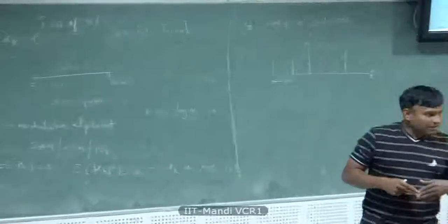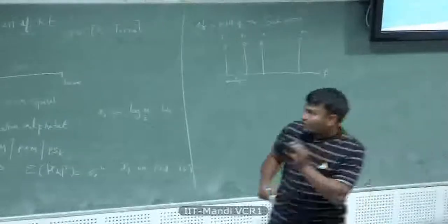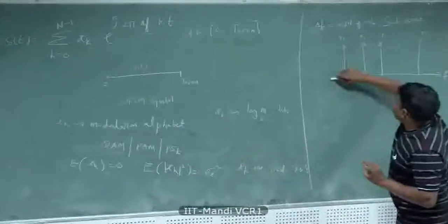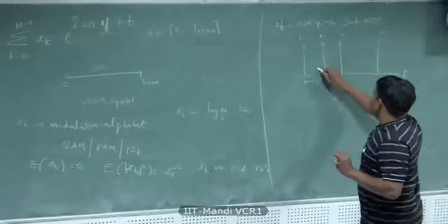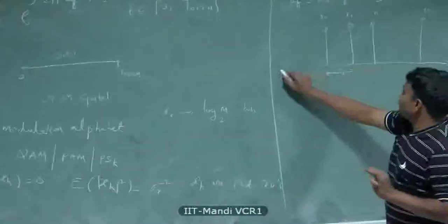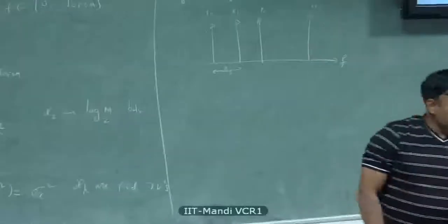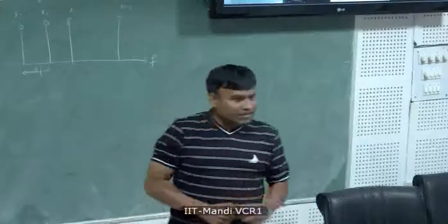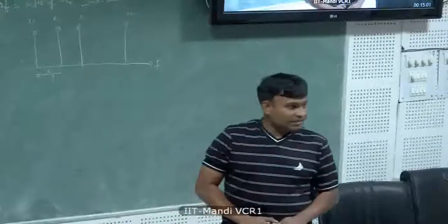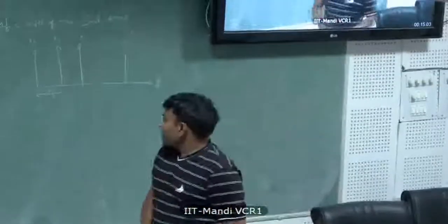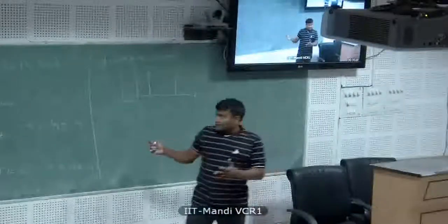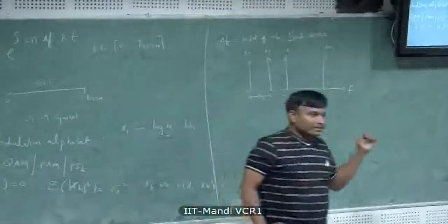So essentially, in frequency domain, to send one complex sinusoid between 0 to T OFDM symbol, you will have something like this, right? Isn't it so? You will occupy much more bandwidth than this single line that is shown here. That's why I said it is a symbolic representation. Okay? So, the transmitted signal is limited in time, and therefore it is not limited in frequency.